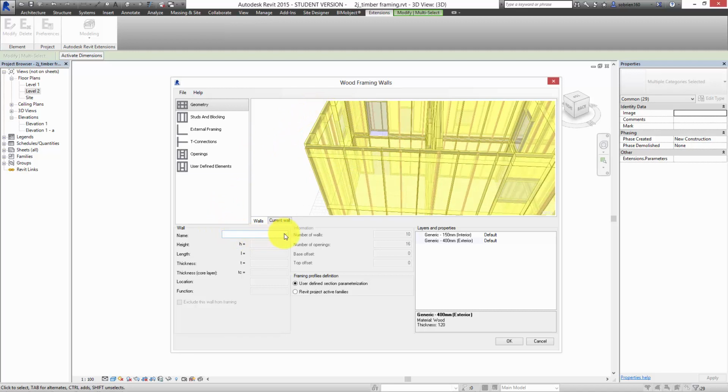So we can choose individual walls in here, and we can kind of play with it. It's giving us default elements in here. It's giving us like standard 150, 400, but we can actually choose Revit families that are in here. So I could choose a column in here that's the right dimension that I already have set up in the project instead. So that's one thing.